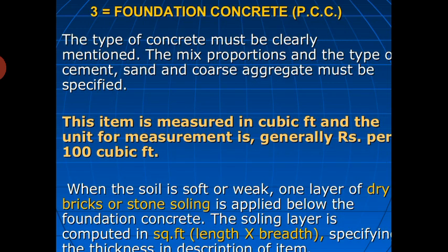Of course, for the foundation concrete, whether it's PCC or another type, you have to mention it always. What type of mix proportions you are using, that also you have to mention, because different proportions have different rates. This item is measured in cubic feet, and generally the rate is per cubic foot.